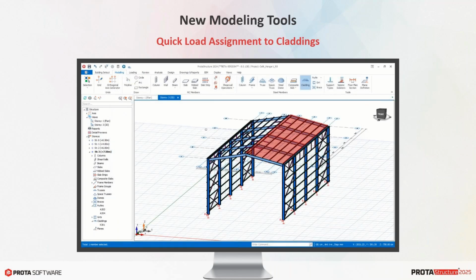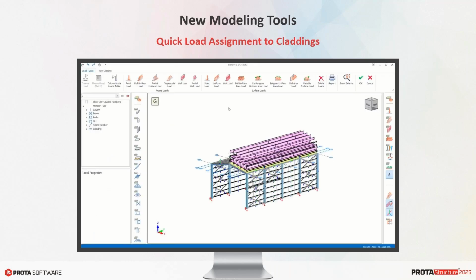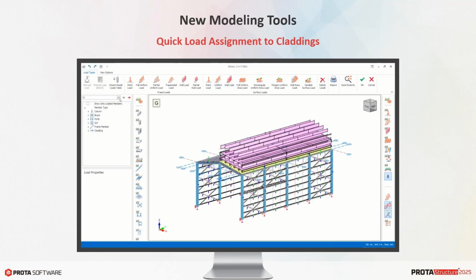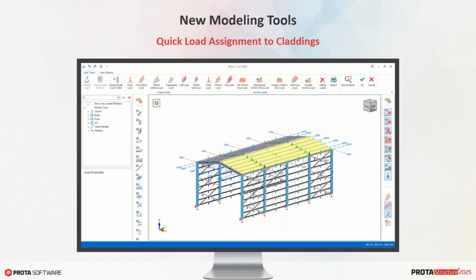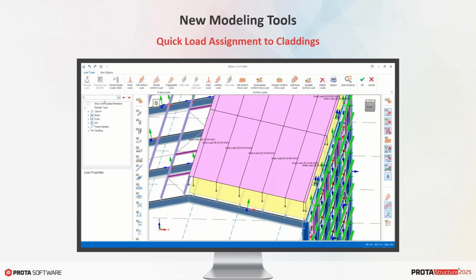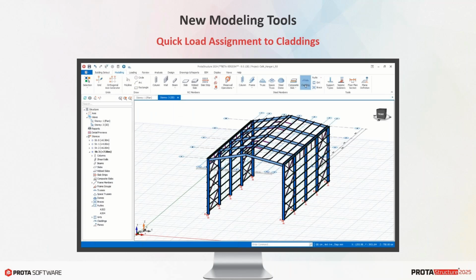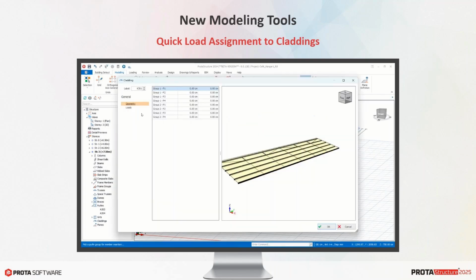ProtaStructure has a very flexible and extensive loading editor, as you know. You can use it to apply any type of load from any direction to any member. If you open up the load editor, you can see the generated load vectors and elaborate the loads further if you need to. Again, you can also create your own manual load cases and combinations in ProtaStructure. And in such cases, if this is your case, then you can still use the load editor to create load vectors defined in manual load cases.